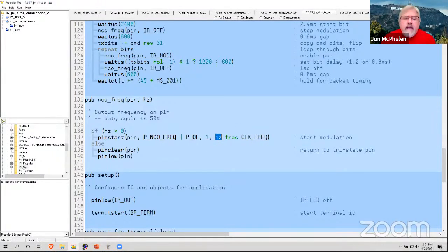Now, you can actually, and I did it this morning, if you want, do it easy with yourself, do a pretend 4-bit accumulator and then put a number, like a 3-bit number in there and add it in. And whatever is in bit 3 of the accumulator, you show your output. You'll notice you'll always get a 50% duty cycle, but your frequency will be dependent on this number. The bigger this is, the lower the frequency.